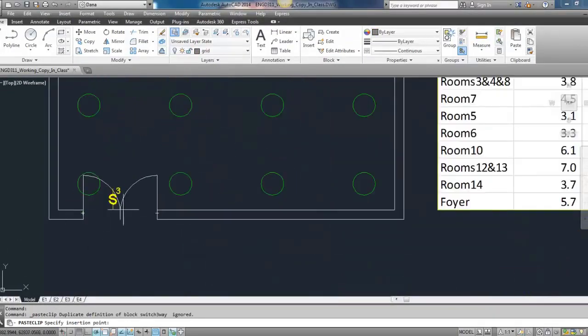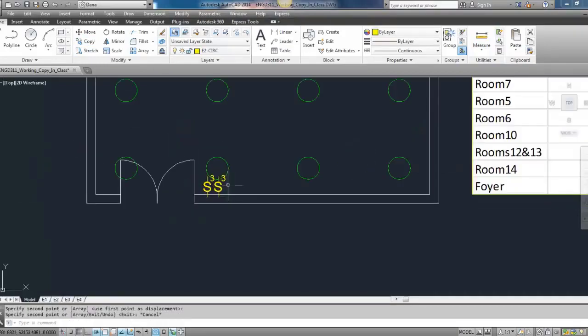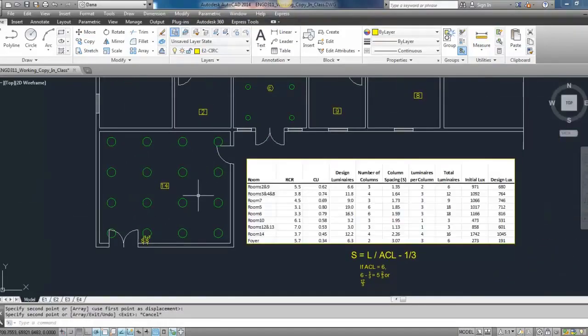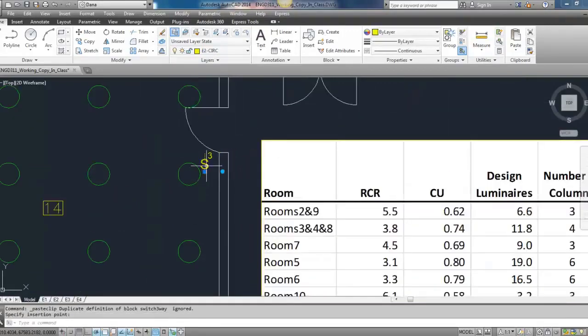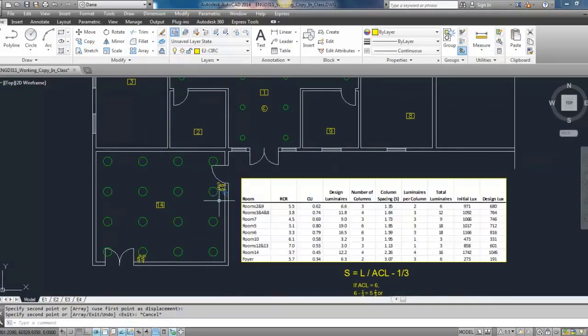So right near the opening, you'll have to select the side for the 3-way switches. I think I'm going to use this side here because it just kind of makes the most sense to me. And we're actually going to make a copy of that. We're going to create 2 versions of it because we need 2 3-way switches at every door here. So let me come in here, rotate this one. And so that's what it's going to look like. You're going to have 2 sets here.